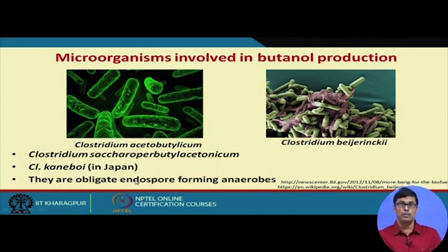Here I want to point out that an obligate anaerobe is a little bit difficult to handle, because a trace amount of oxygen present in the fermentation broth will kill the microorganisms. So you have to totally remove the dissolved oxygen from the fermentation broth, and only then can your organism grow in the fermentation media. This is the only disadvantage we have. Another problem with the anaerobic fermentation process is that the rate of reaction is quite slow as compared to the aerobic fermentation process.